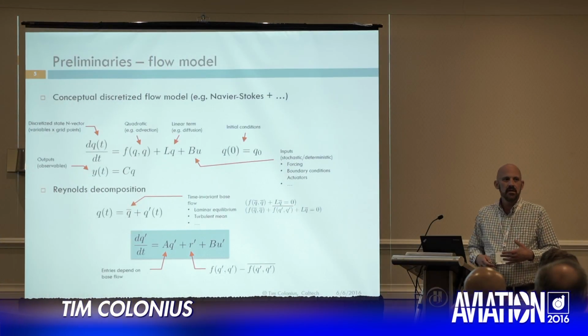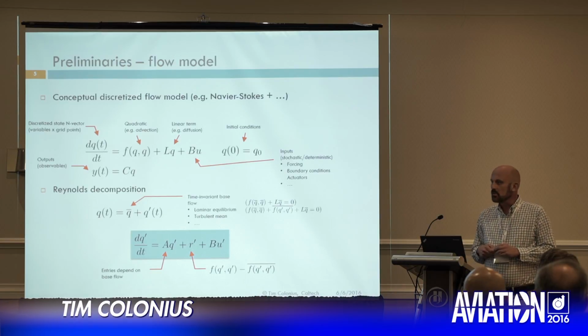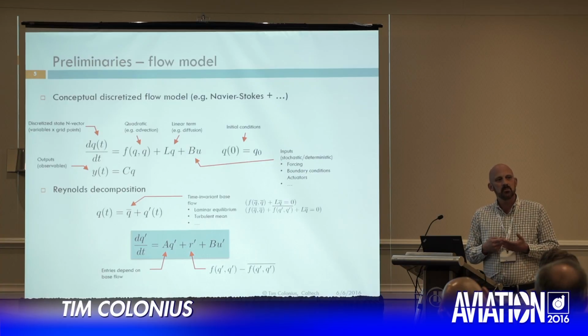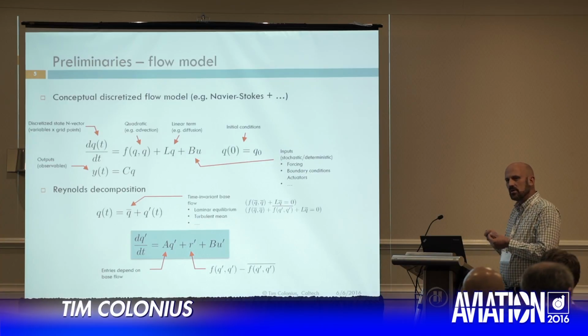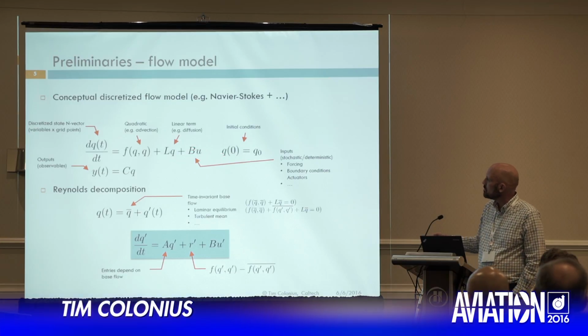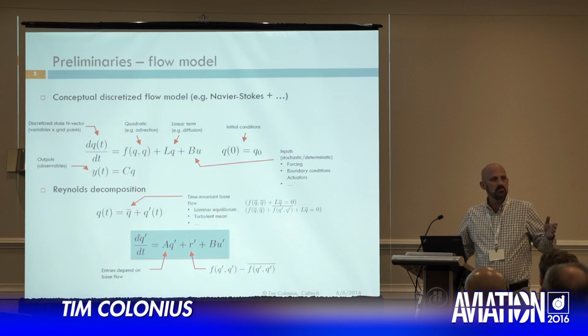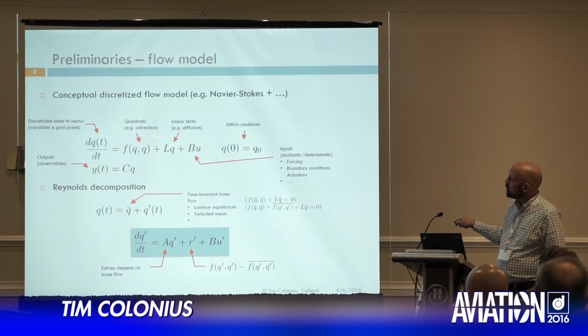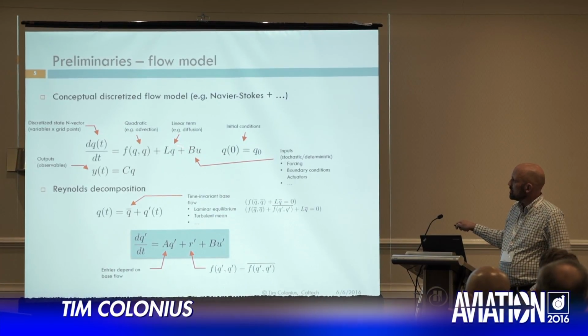They might represent some kind of a forcing of the flow field. Oftentimes in doing DNS and LES, we have to excite the turbulence somehow. We have to add a volume force somewhere and tickle the flow to excite the turbulence. So that would reside in this input term here, as well as things that come from, for example, inhomogeneous boundary conditions, which in the discrete world would be written as a term in the equations like this.